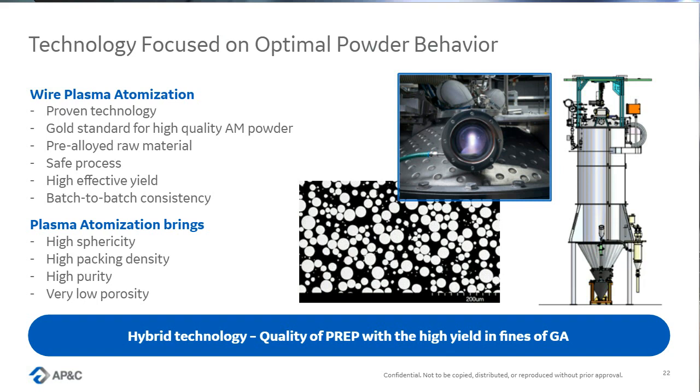It's a very safe process that is melting only the tip of the wire. So that's ideal for reactive metals and high melting point metals because we've got lower time at high temperature compared to a crucible, so less chance of contamination with either surfaces that it can touch or contamination in the gas you're using.